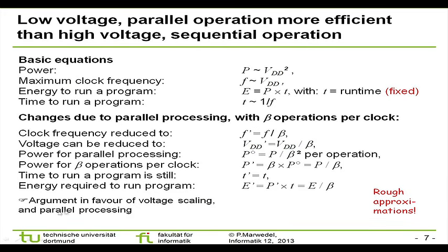So, if I look at the slide again, this certainly puts up an argument in favor of voltage scaling and parallel processing done together. I can do parallel processing, and along with that I can do voltage scaling. So, that is another architectural way of dealing with power.